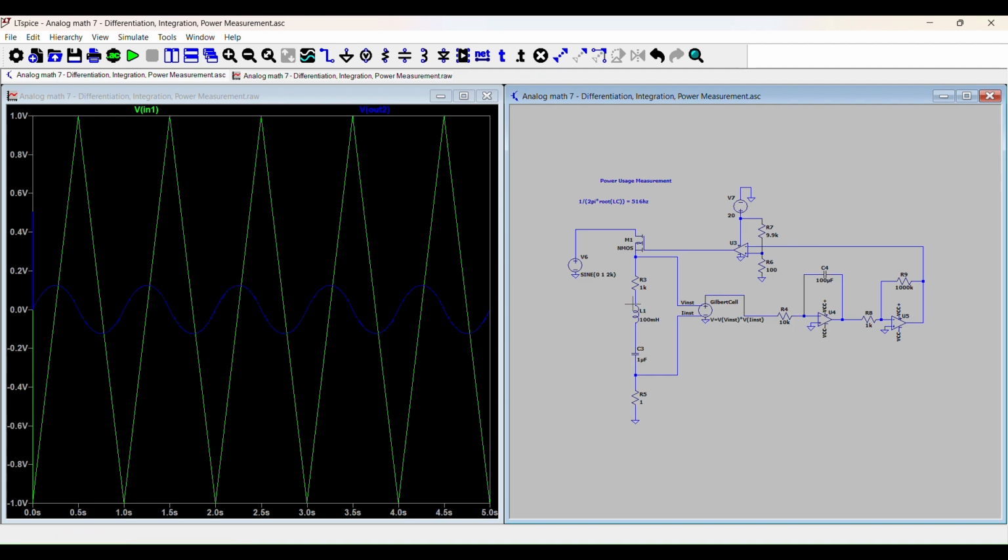And this is the power source. It's basically inputting a sine wave. And I am taking the voltage across the component with respect to ground and the current across it by taking the current with respect to a shunt resistor that I put in series with the component. This shunt resistor is 1 ohm, so it doesn't really change the voltage at all, and it doesn't impede the current very much, but we can use it to measure the current.